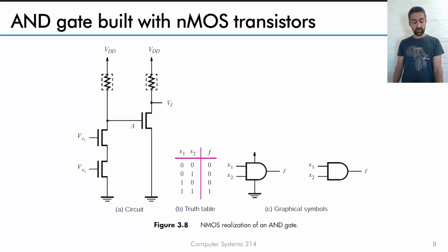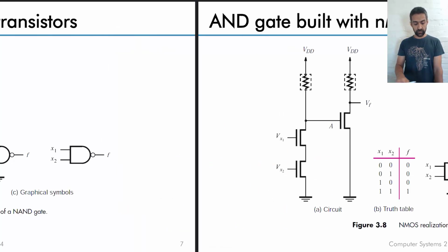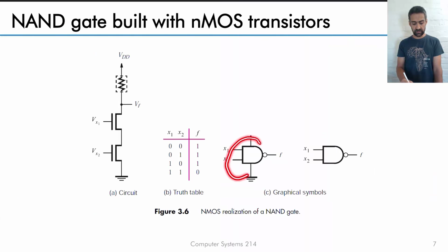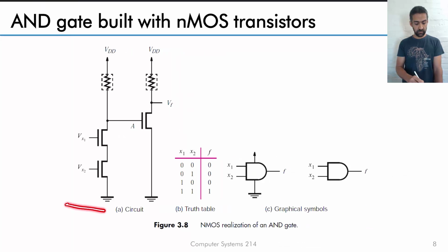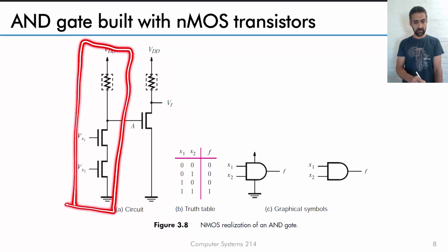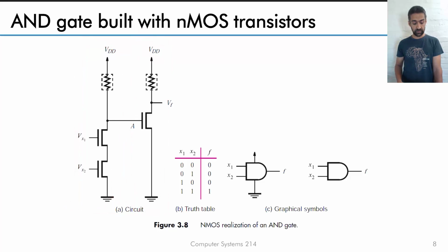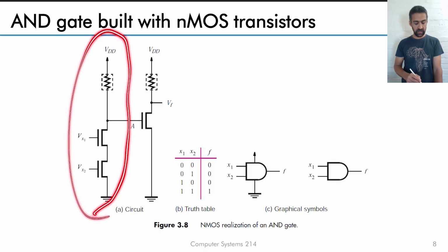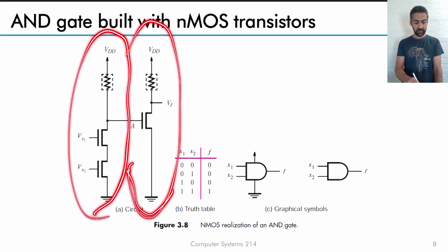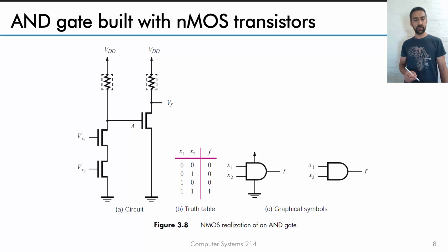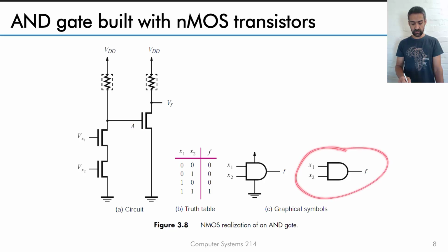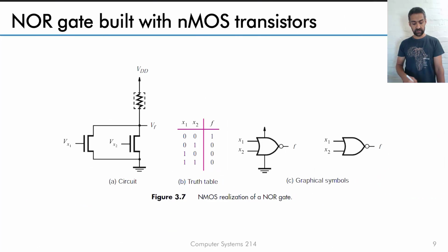Let's just consider how to build an AND gate. Now, obviously, just going back here, this is an AND gate with an inverter. So to make an AND gate, we make a NAND gate, and then we just stick an inverter onto its output. So this will behave like a NAND gate, and this will behave like a NOT gate. So the combination of the two just gives you an AND gate. And this is what it looks like. This is the implied circuitry, as I said before.